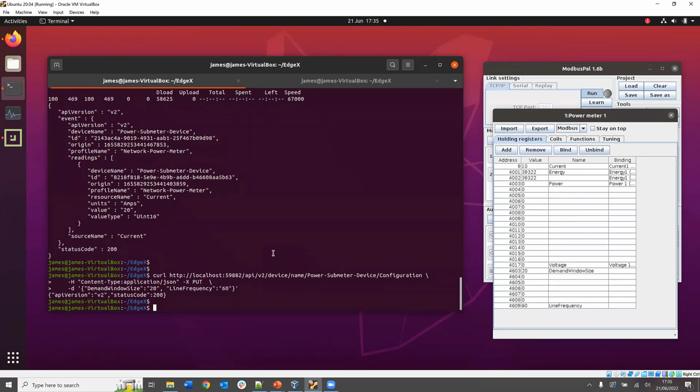Which is good. So we've successfully modeled the read-write capability of our devices, and we're accessing those data points at sensible periods, because we've got it accessing by default every 5 seconds for the data values, and the configuration values only every minute, to try to minimize the load on the device. Okay, that's good. Hope that all makes sense.